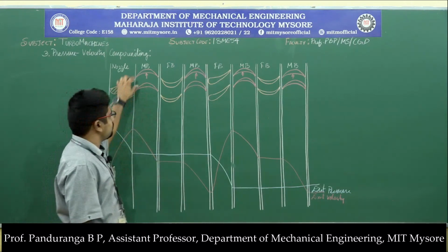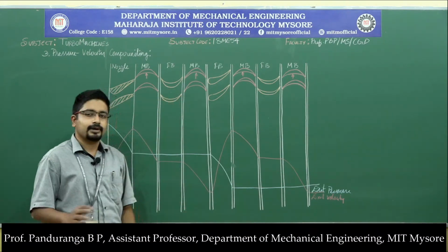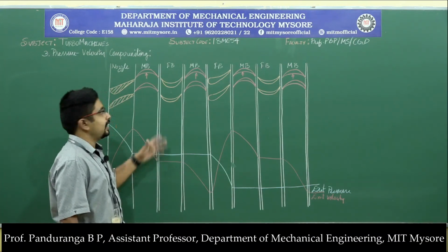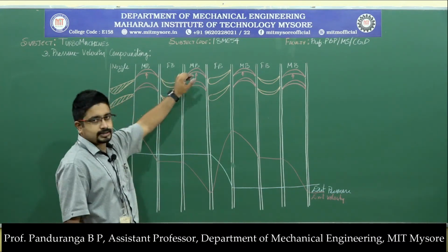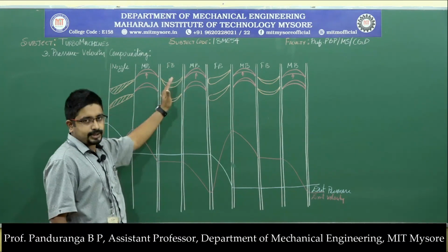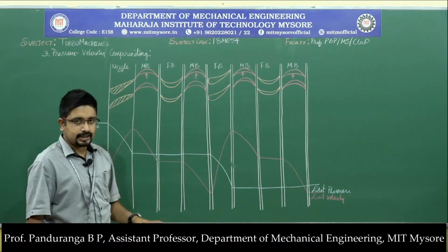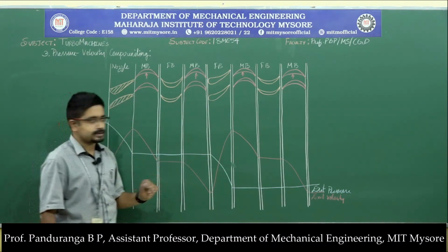So there is no change in the flow area, so the pressure remains same. Because of that, the pressure energy remains same. And then the steam enters the fixed blade. Again here the blades are symmetric in structure, so there is no change in pressure, and since the blades are fixed, the blades are not absorbing any energy, so the kinetic energy or the velocity also remains constant.